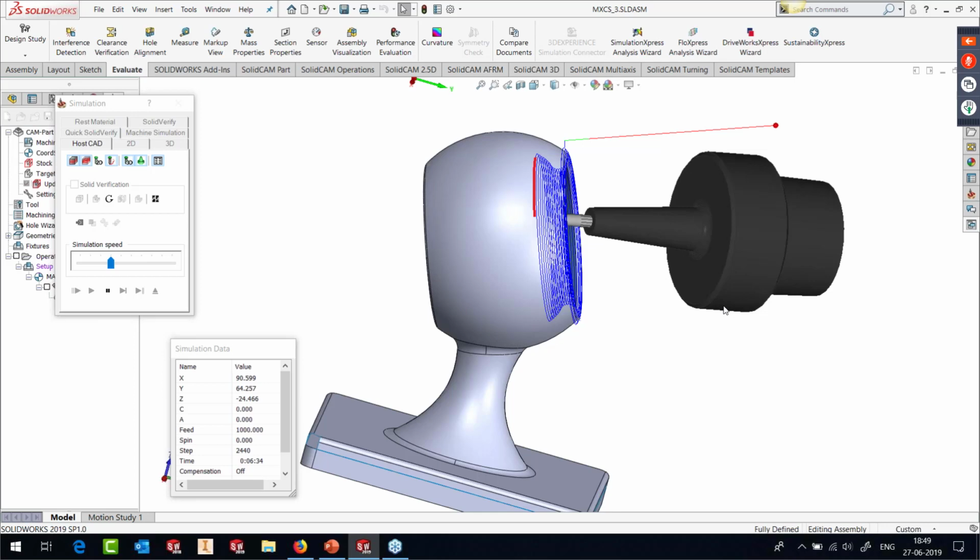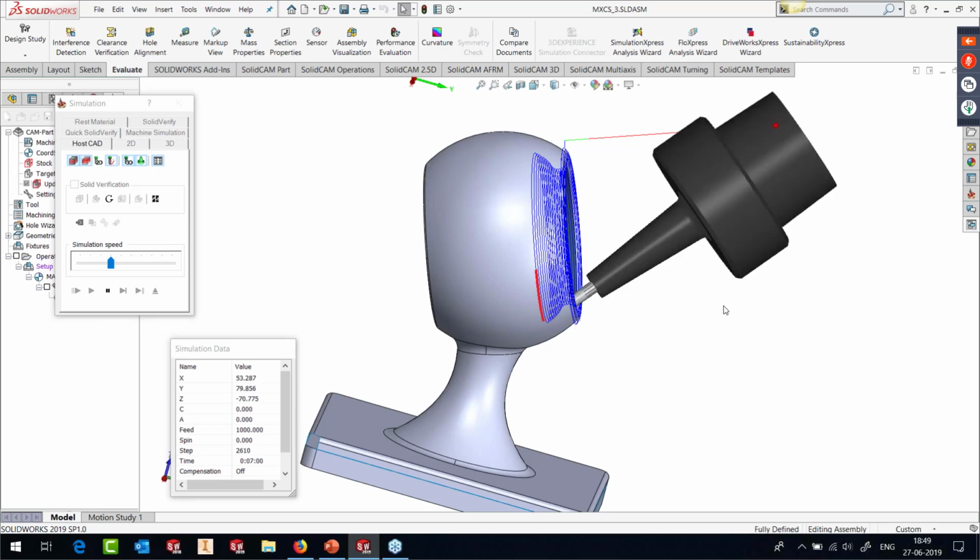Okay, so it's pretty nice. Generates extremely high quality of surface finish because it's using extremely consistent spacing between two strands of the toolpath. And on top of that, we have the auto tilt in the gouge check, and that takes care of collisions between the tool, the geometry, the holder, and the other areas that are involved into this. Okay, so that's how it does the parts like this.